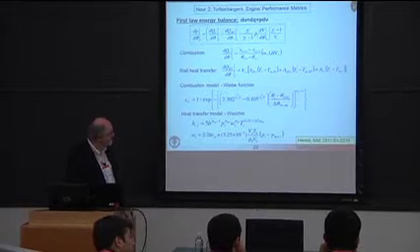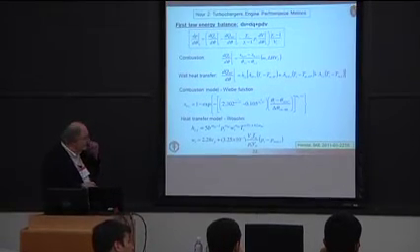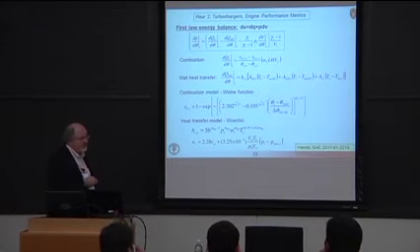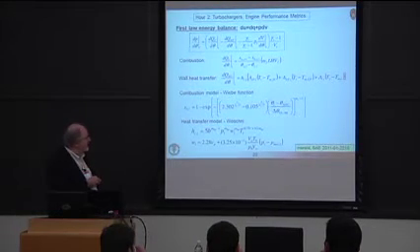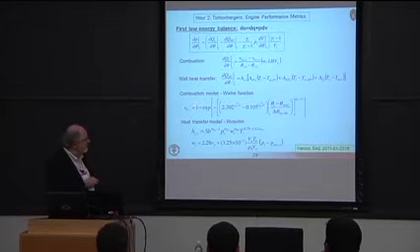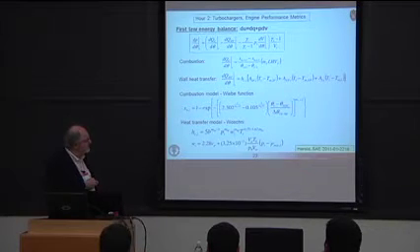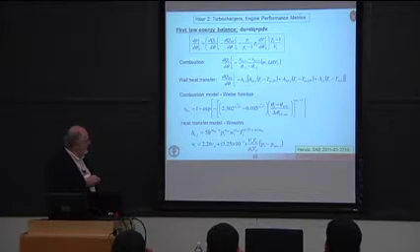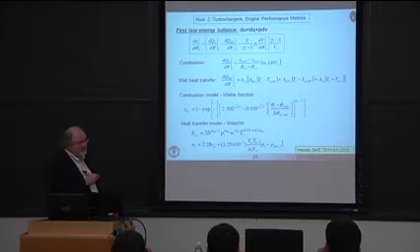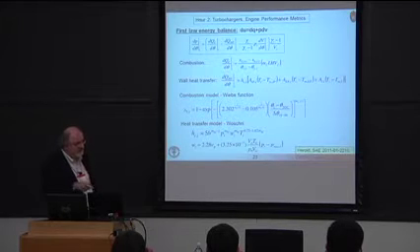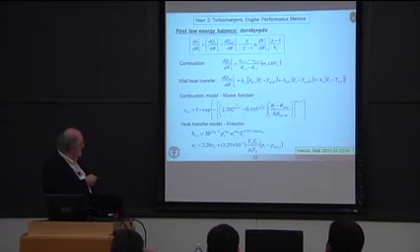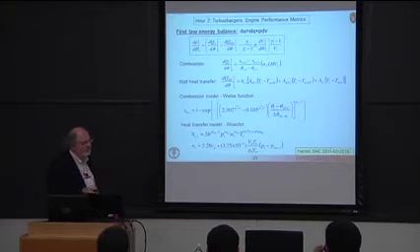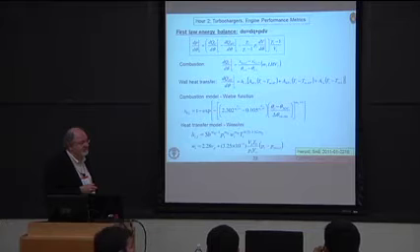Yeah? How do you define the Wiebe functions for different engines? Yes, so essentially it's a correlation. You'll see, though, that people generally pick a term that looks like this for a single heat release type of combustion. For more complex heat release, where we have that premixed burn and then diffusion burn and then a late burn, you'll sometimes see a 3-part Wiebe function. So it's all empirical and curve fitting, basically.